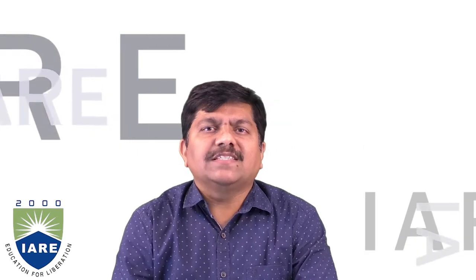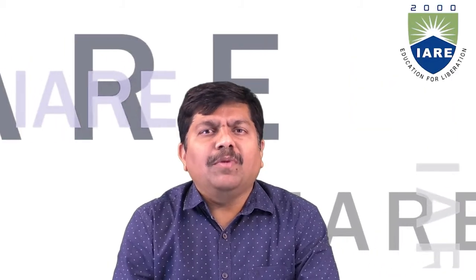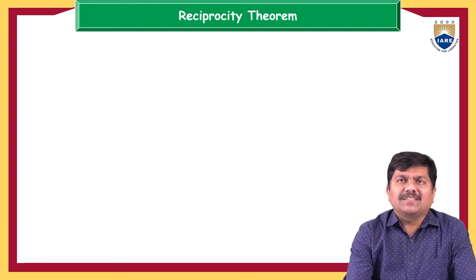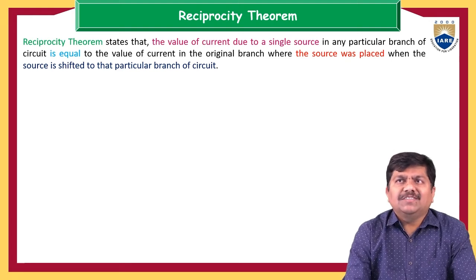Let us talk about this reciprocity theorem with some simple statements and one simple problem, which I am presenting for better understanding. So let us start with the statement: the value of the current due to a single source in any particular branch of a circuit is equal to the value of current in the original branch where the source was placed, when the source is shifted to that particular branch of the circuit.